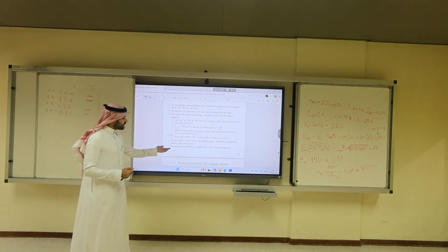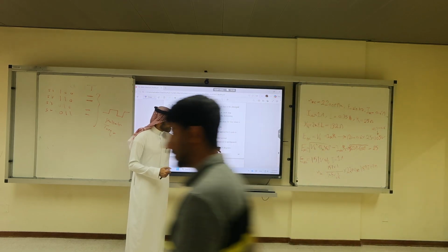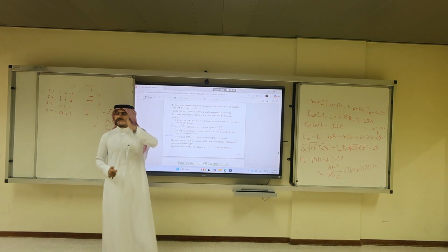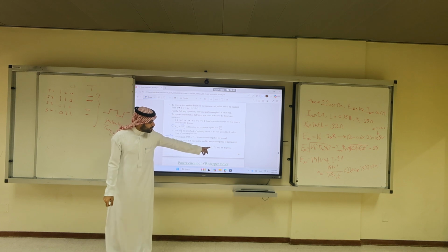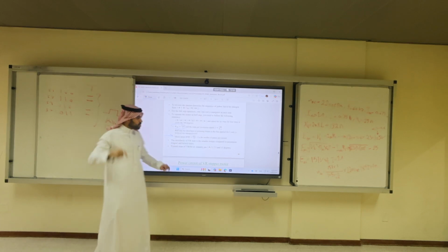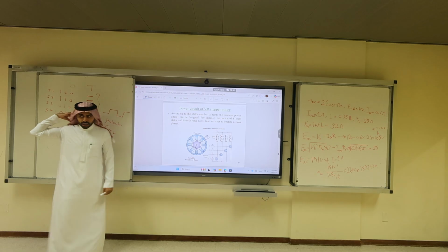And there are some common step angles, for example, 1.8, 5, 7.5, 15 degrees. In our example, we had 30 or 15 degrees because it's easier to operate. But if you have, for example, 5 degrees, you'll have very long tables and you need more switches. How is this achieved? What do the power electronics look like?